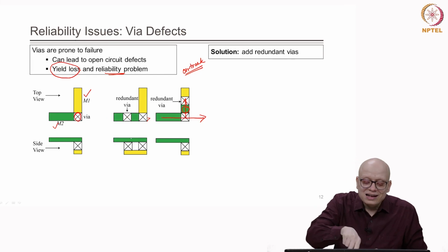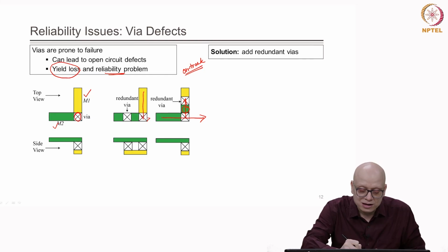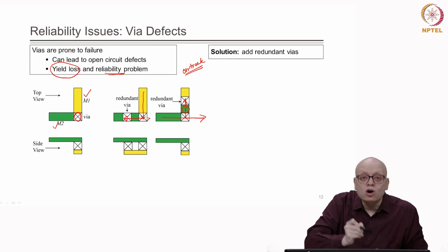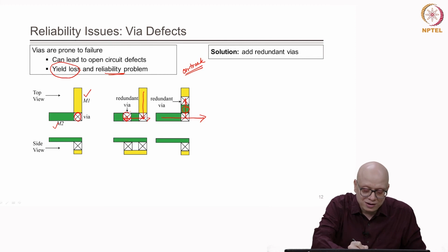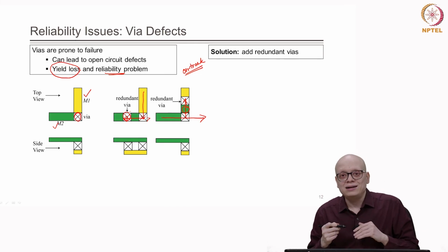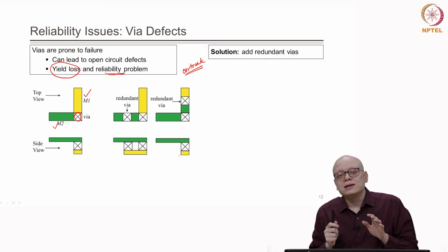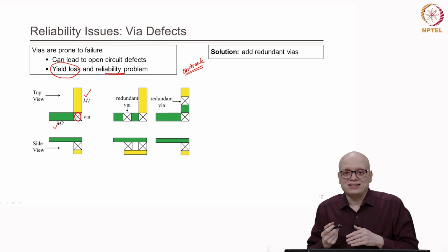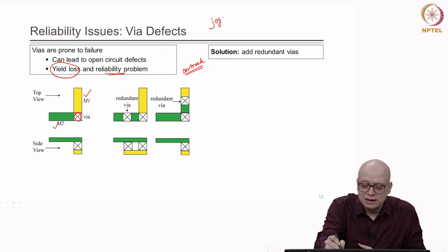Similarly, we can do the same for the M1 layer also. This is the M1 layer, and the M1 layer is below the M2 layer. So, we are extending along the non-preferred direction, along the horizontal direction, and then we create a via here. So, these vias are on track vias because we are using the same track. For short distances, it is usually allowed that the routing is done in the non-preferred direction, and those are known as jogs, J-O-G-S, jogs.